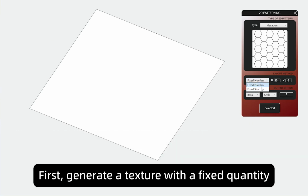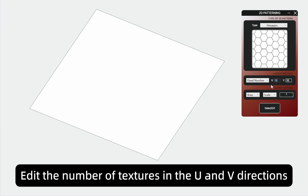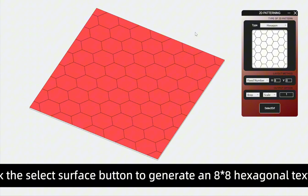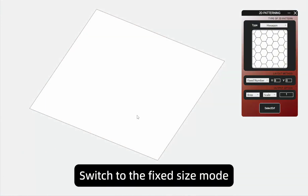First, generate a texture with a fixed quantity. Edit the number of textures in the U and V directions. Click the Select Surface button to generate an 8*8 hexagonal texture. Switch to the fixed size mode.